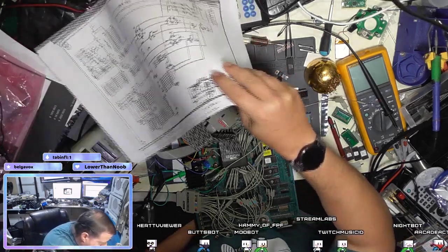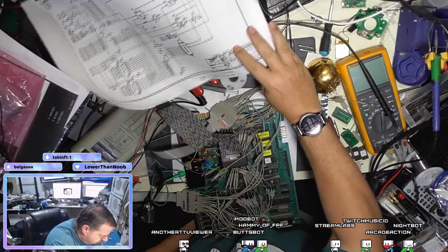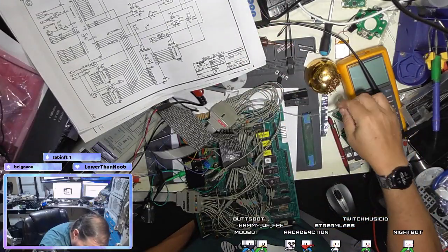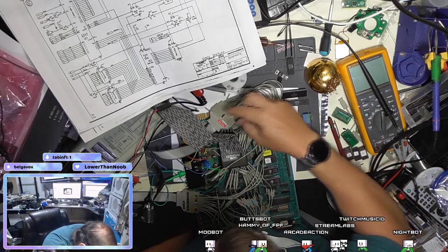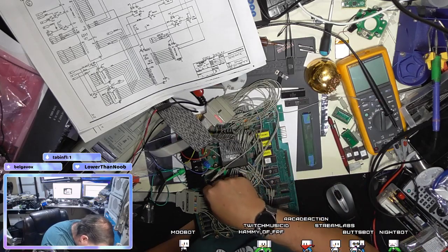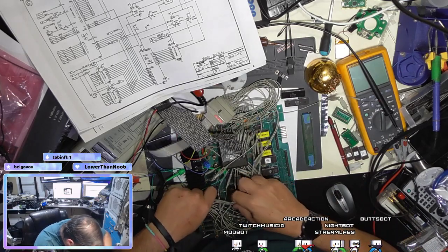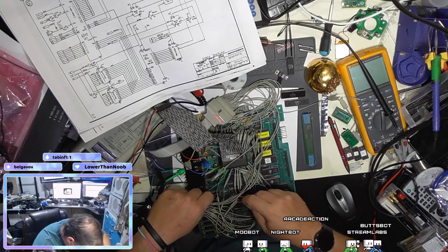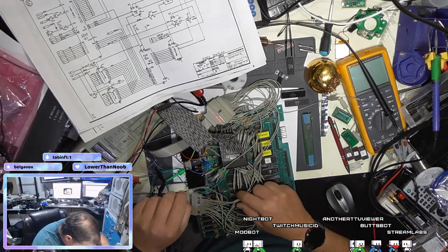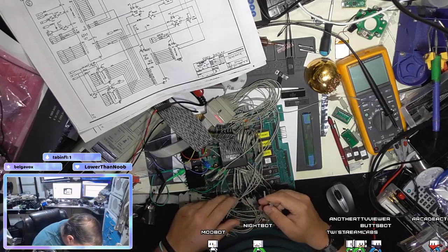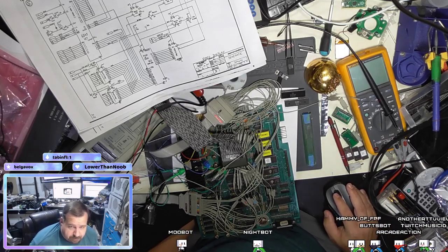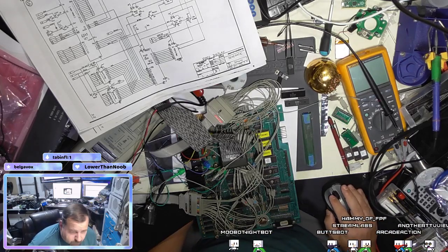I need to add the clock signal to the clock pin and switch to a state analysis. So we use this clock pin here, which is tangled in with all these other pins. The Fluke troubleshooter is hooked up, but unfortunately I do not actually need to use it anymore. But I'll leave it hooked up anyways.